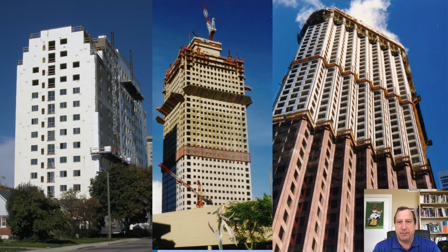But these images I'm showing you here are for relatively tall concrete buildings, which are called pierced shear walls. A large proportion of the concrete does have holes in it. However, there's still enough concrete and none of the holes are so large that you don't get significant benefit of this rather significant area of the entire perimeter of the building.